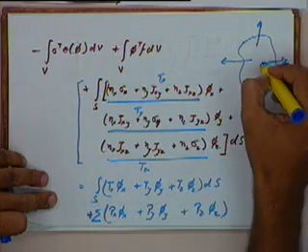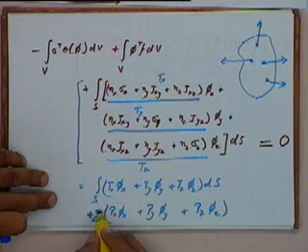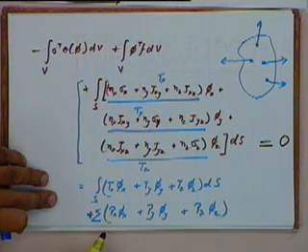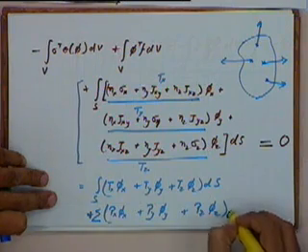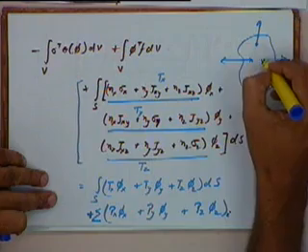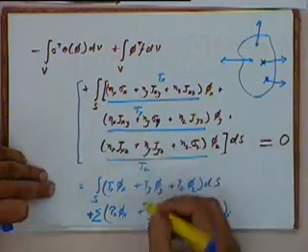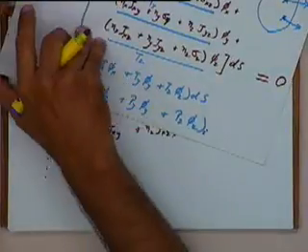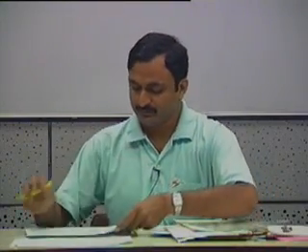For each of these point loads, I will get a term like this. So I will carry out a summation over all the point loads. Okay, and these phi i's will be the phi at each point. Okay, so if I make these two substitutions, this integral term